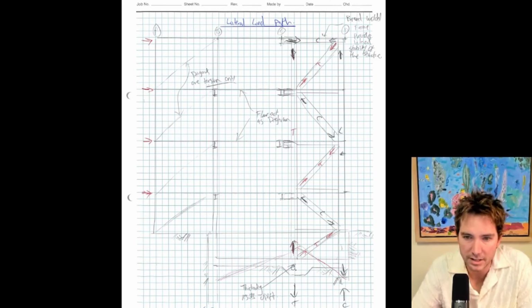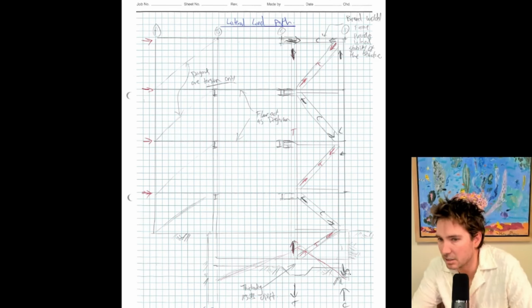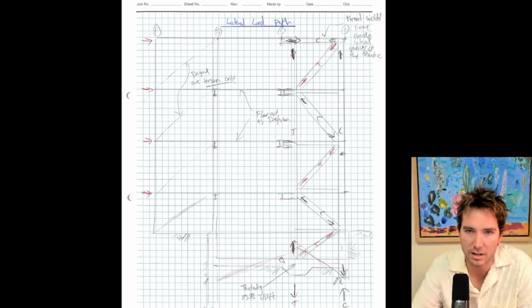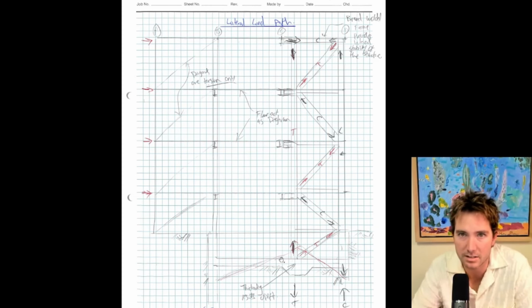There's a local thickening in the base slab. In this particular instance, it will be resisting uplift, and I've noted that here. And again, it's just compression under this particular column, which actually lands at the top of the D wall. Then that load goes through the ground and then tension here. So that's the lateral load path of my second scheme.